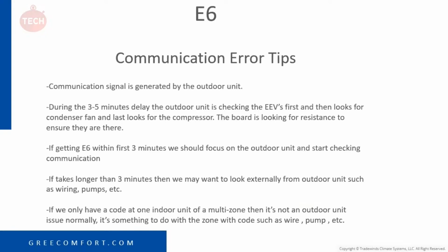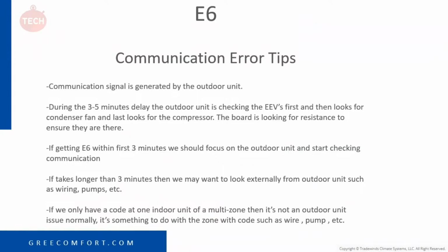So E6, of course, is a communication error. A couple tips to check before even diving into it really deep. Obviously, the communication is generated by the outdoor unit. During the first 3 to 5 minutes of the delay, the outdoor unit is checking the EEVs first, and then looks for the condenser fan, and last looks for the compressor.